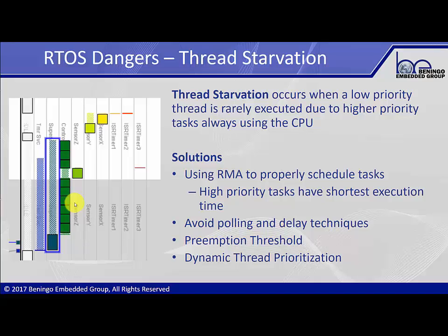After we set up the Tracealyzer tool, I'm going to show you how we can actually get some of this timing information and start to zero in on maybe where we have issues in our system. You can imagine if I trace a whole bunch of events and then look through a trace like this, if I see long traces like this, it'll make me realize that there's probably some thread starvation going on here. You could actually click on it and then discover what the latency time is for the task to get access to the CPU.